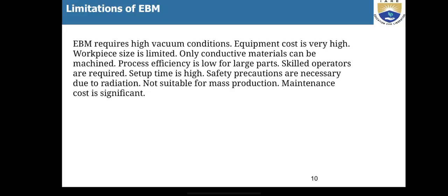Limitations of EBM. EBM requires high vacuum conditions. Equipment cost is very high. Workpiece size is limited. Only conductive material can be machined. Process efficiency is low for large parts. Skilled operators are required. Setup time is high.